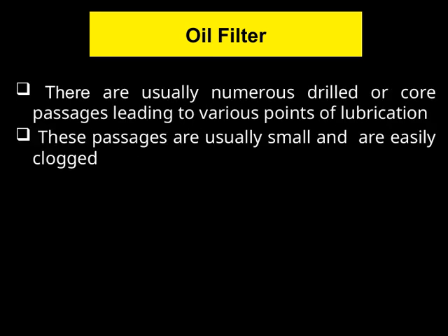There are usually numerous drilled or core passages that lead to various points of lubrication within the system. These passages are typically quite small, which is important to note because their size makes them prone to clogging. When these passages become blocked, it can significantly affect the flow of oil and, ultimately, the performance of the machinery. That's why an oil filter is so critical.